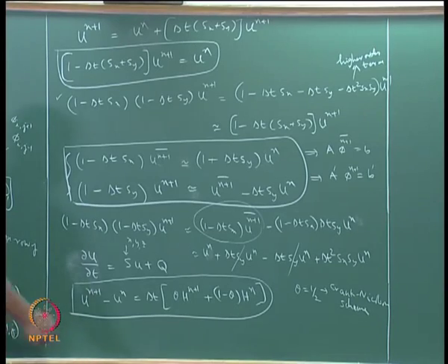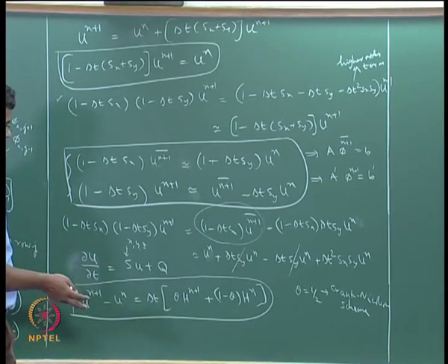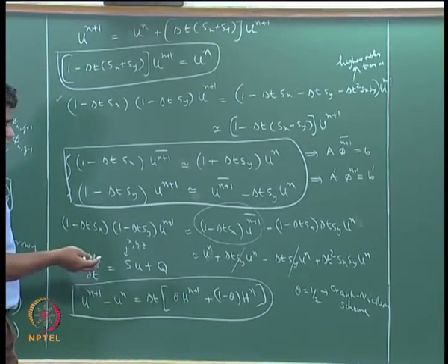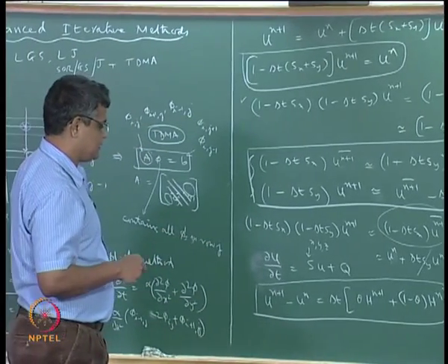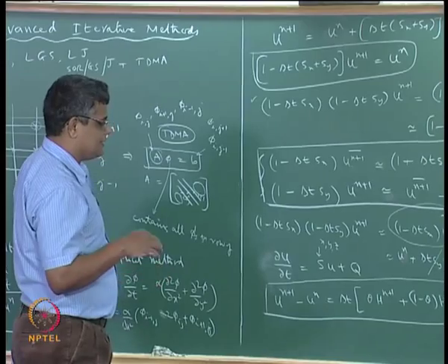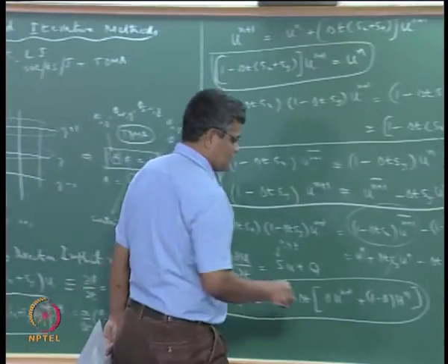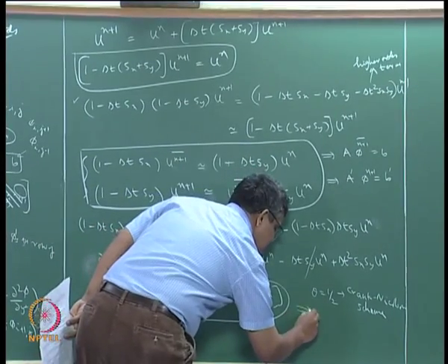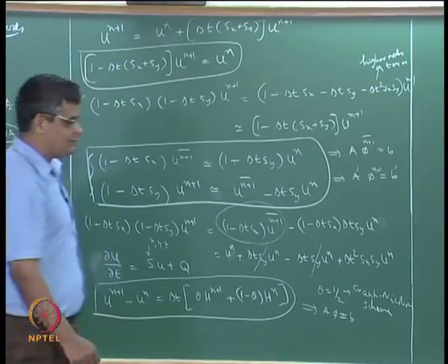And so we can expect in the general case, for second order accuracy of the diffusion and first order accuracy of the upwinding scheme of the convection term, a 7 diagonal matrix. So this can be converted into something like a phi equal to b, which will have 7 diagonals.